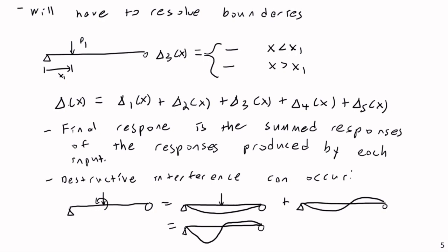So really the only way to do that is to use your mathematical tools. You'd have to take the derivative of each of the pieces, within each bound, to find the actual maximum. It can be tedious, yes, but that's how you have to do it. Or alternately, you could plot it. If you have a nice computer plotting tool, you can take your function, plug it in there, and simply plot it, and then look graphically at the maximum, or at least use that to find where your maximum deflection would be, et cetera.